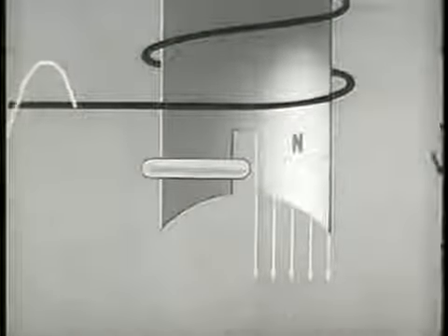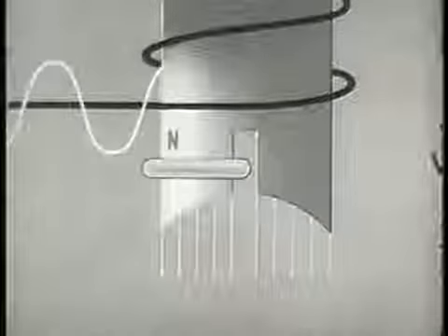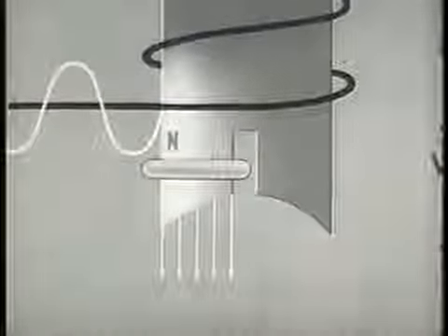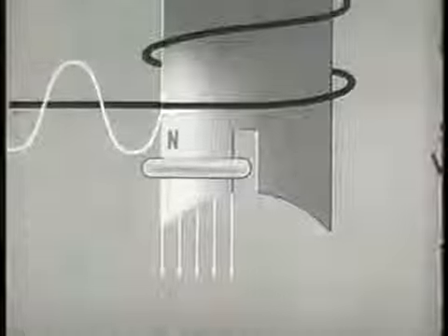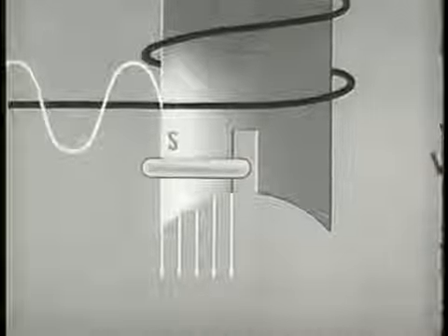Lines of force will emerge from this unshaded section of the pole face first. The inductance caused by the ring makes the shaded portion of the pole lag behind. This alternating pulsating action creates a phase difference within the pole.